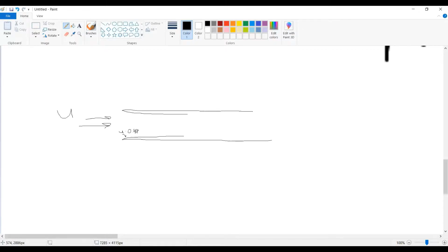And the reason why the boundary layer is so important is because within the boundary layer here, there's viscous forces. And that's why that area is slower. But outside of the boundary layer, there are no viscous forces. And so what's happening is that as the flow goes along, the boundary layer is developing and is getting a little bit larger. And then there comes a point where the boundary layers are essentially fully developed, let's say here.